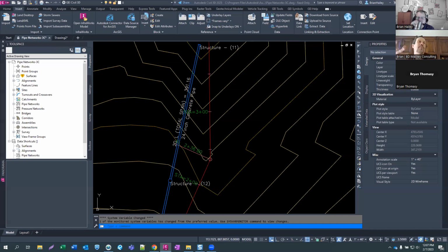For me, I was on the fabrication side of things, so I had computerized equipment that could be accurate to the 1,000th of an inch. So I model that way in Revit. Everybody says I'm stupid because they're not going to build it that accurate on site. It's like, yes, but compounding errors can add up, so I'd rather make sure I'm as accurate as I can be. I go out 10 decimal places in Revit when I dimension. If I'm not seeing all zeros there, then I've modeled it wrong and I fix it, because I'd rather have it correct there and let somebody else screw it up on the site, but there's nothing on me.